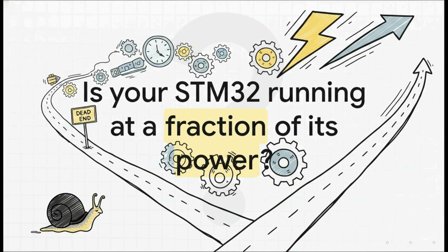So let me ask you something. Is that powerful STM32F4 on your desk actually, well, running at a snail's pace? And chances are, if you've never messed with the clock settings, the answer is a big yes. Right out of the box, these things wake up in a safe, slow mode. They prioritize just working over raw speed. But that incredible potential, we're talking up to 180 megahertz, is just sitting there, waiting for you to unleash it.